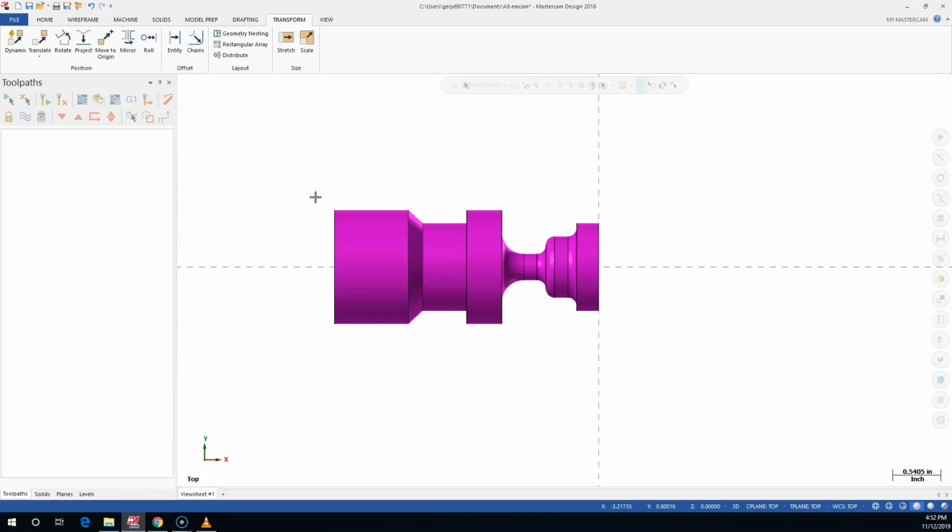If it came in off of a drawing file, you would need to measure some geometry and check that it's not a 1:2 or a 2:1, something like that, because usually you program the whole thing, and what always happened to me was, oh, I took my 1/2-inch drill, and the thing was this little tiny speck in this huge bore, or it just wiped out the whole part when I drilled with the 1/2-inch drill, or 1/4 or something along those lines. Something that gives you a visual reference to your scale, and all of a sudden it's all over the place. So make it a habit of measuring a couple of things.